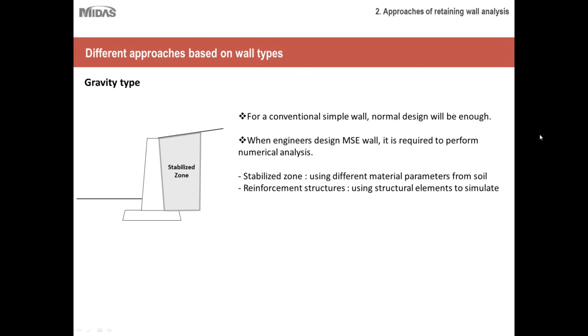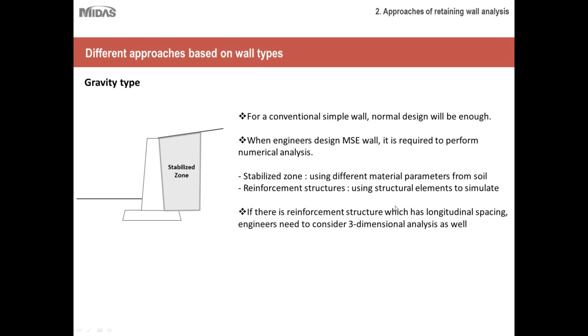So just briefly going over what I just said, for stabilized zone use appropriate material parameters which are different from the soil strata, and for reinforced structures, that is the retention system like tiebacks, anchors or soil nails, use proper structural elements to simulate it.